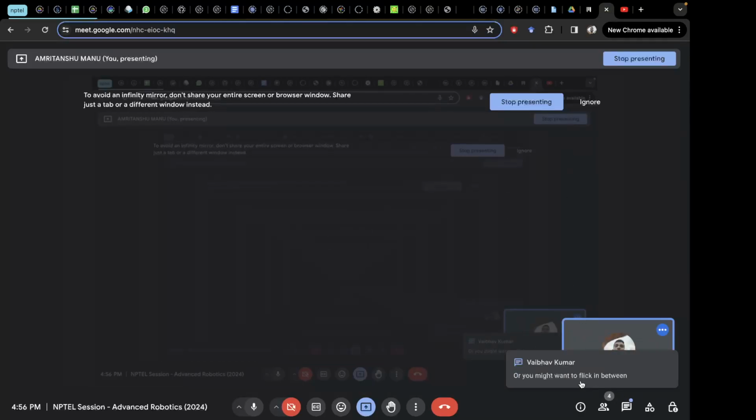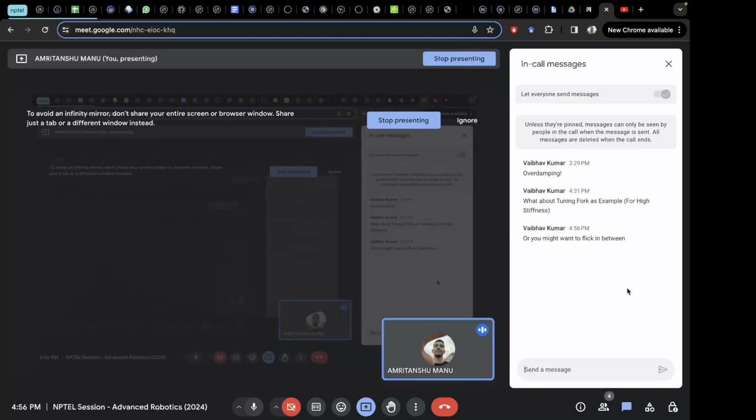By flick, I guess you mean some additional motion in between point A and point B. So in order to make your trajectory flexible, or add more features into it, you will need more degrees of freedom. And by degrees of freedom, I don't mean degrees of freedom of the system. I mean more parameters of your trajectory. One solution could be to use an even higher degree polynomial, one polynomial but of even higher degree.